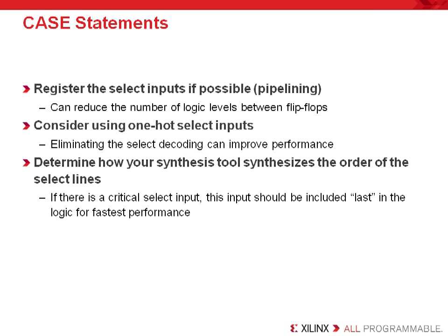Lastly, test out building a mux using a case statement with your synthesis tool. Usually, synthesis tools will put the last signal listed in the case statement in the last level of logic, meaning that it will get the shortest path.